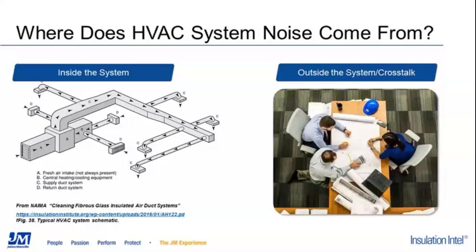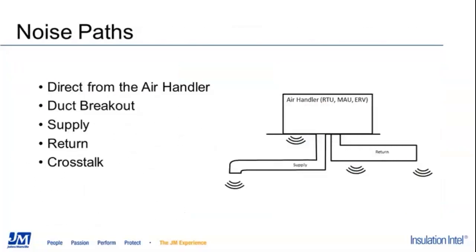So they can generate airborne noise, but it's also important to note that this flow of air can also create its own regenerated noise. That could be through undersized ductwork, VAVs, heat pumps, elbows, transitions, junctions, diffusers, and even leaks. You may have selected a quieter unit, but that does not equate automatically to having a quieter system. So this noise can enter into noise-sensitive spaces in a number of ways.